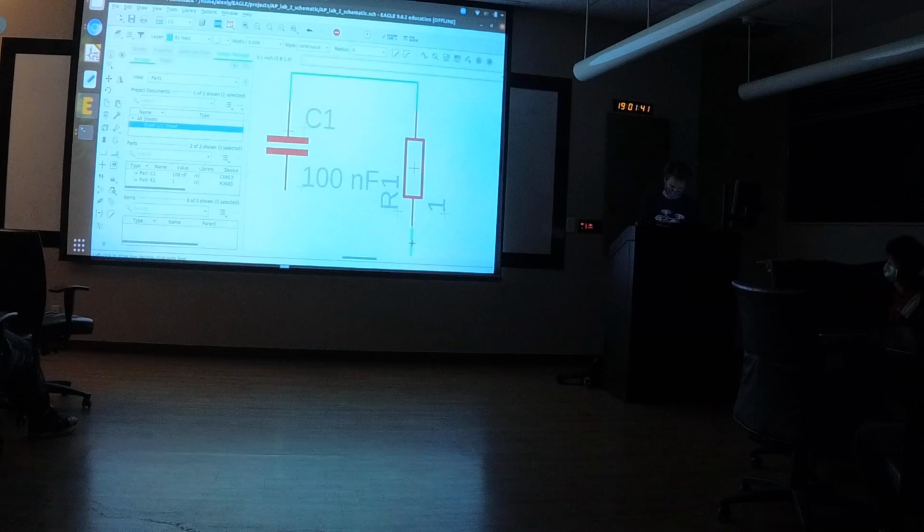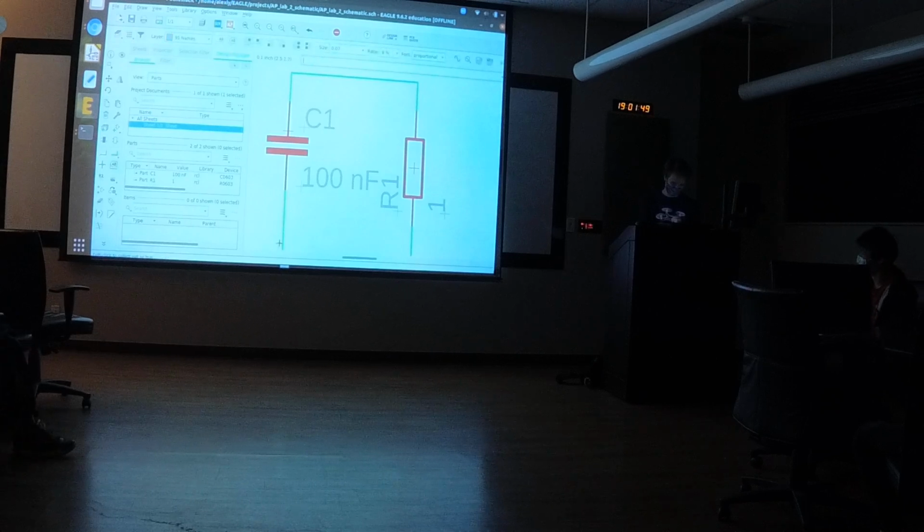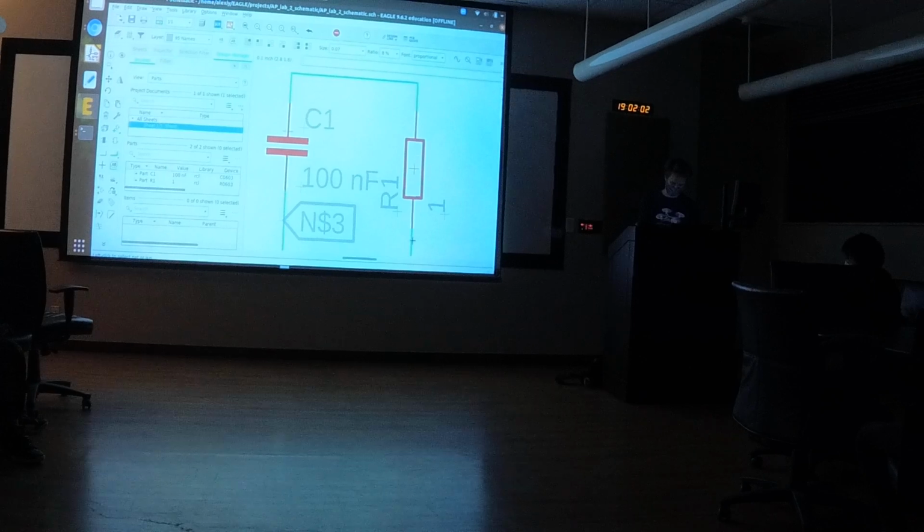So in order to connect it to a, okay. You know what? Let's see. I'm starting to see your point now. Eagle is not that cool. Yeah, it isn't. Okay, so we go back to label. We add a label to this wire. And you can add it, and you right click to rotate it, but we're not going to rotate it. So this wire is labeled $3. Then we add another label to this wire, and we're going to label it $2.